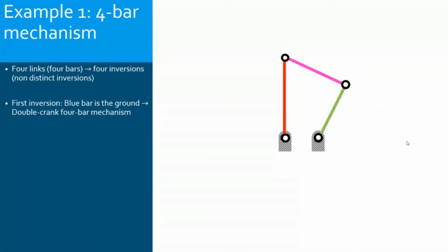Now, as I have said, the kinematic diagram is just a representation of the most important things that can help you study the kinematics. So the ground mostly is not represented itself. I don't need to represent the full body of the ground. What I need to represent is only the connections with the ground.